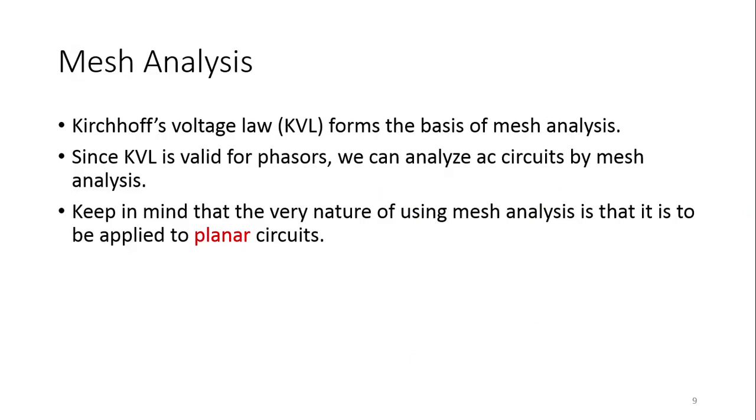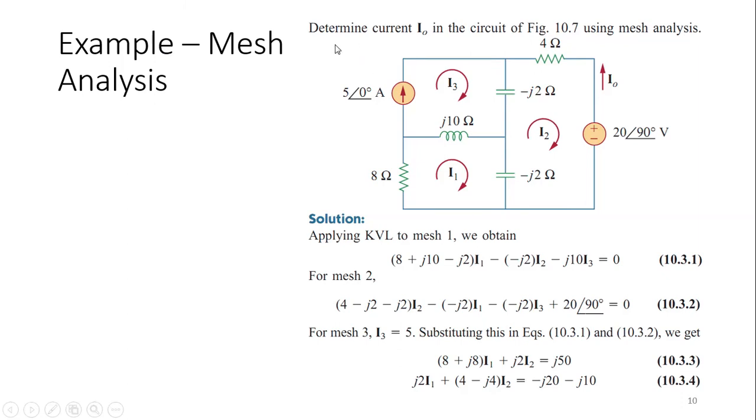So next we move on to mesh analysis. Mesh analysis is based on KVL, and as KVL is equally valid for phasors, as we have seen already in our previous lecture, we can solve AC circuits with mesh analysis techniques also. One thing to keep in mind is that mesh analysis is to be applied to planar circuits. We have already seen the details in our previous course lectures. Planar circuits are those which can, as a simple explanation, be represented in a two-dimensional plane.